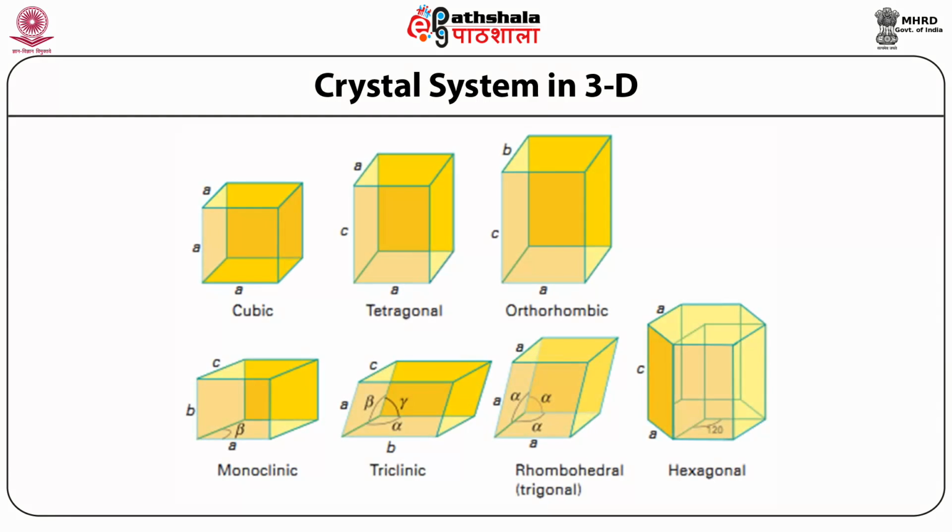Crystal systems in three dimensions. As you can see, since the choice of unit cell is not unique, we can define any unit cell of any shape as long as it contains one lattice point. However, once we start defining various shapes, we come up with 7 categories called crystal systems in which all possible unit cell shapes would fit, provided the space filling criteria is fulfilled. So 7 crystal systems are known and shown in this figure.